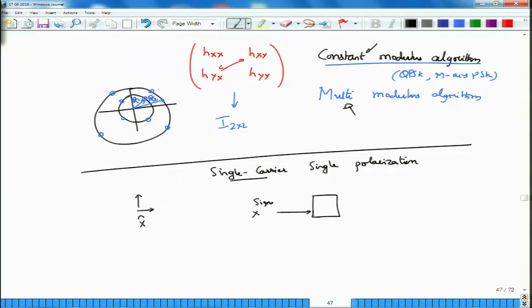So, let us say this is the signal that we have received, and then I need to have a local oscillator as well, correct. So, let us say this is my local oscillator, this is the phase diversity receiver. This is a shorthand notation I am using, it is not really a correct notation. Let us say this is all x polarized, the output of the local oscillator will have some amplitude of square root P_LO, whereas the input will have the same polarization, which we can call either E_S(t) or A_S(t), it does not matter.